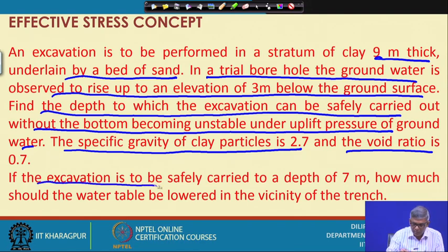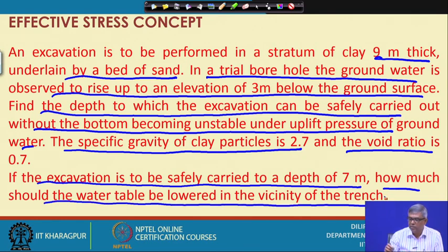If the excavation is to be safely carried out to a depth of 7 meter, how much should the water table be lowered in the vicinity of the trench? I have mentioned that by lowering the water table, sometimes effective stress will be increased, and that is the requirement here. So, I will sketch this one.